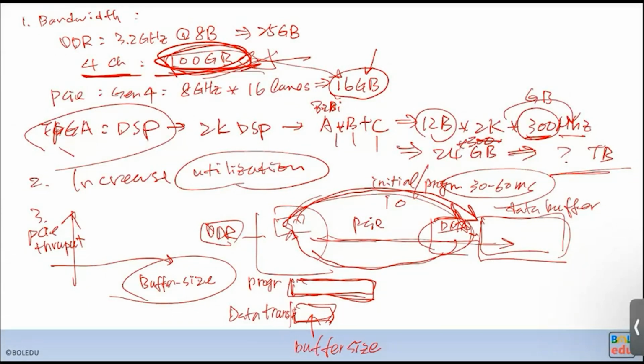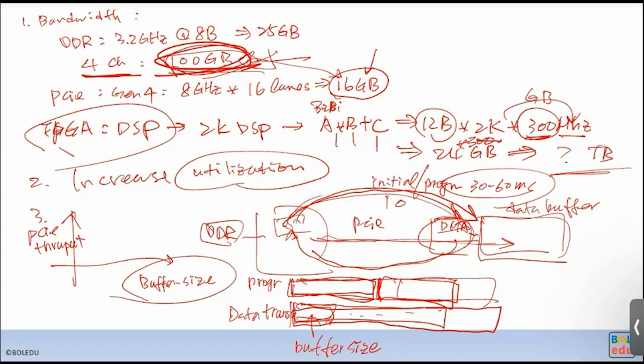If the programming time is greater than the data transfer time, then you will have the PCIe bus idle. That's the reason why you want to increase the data buffer, so that it takes that much time to transfer across PCIe.